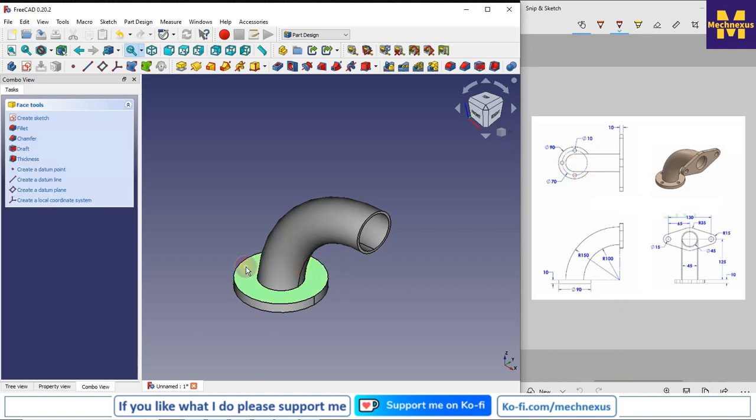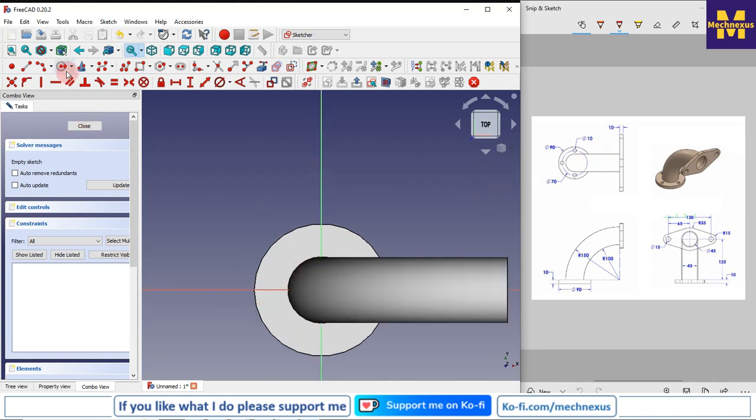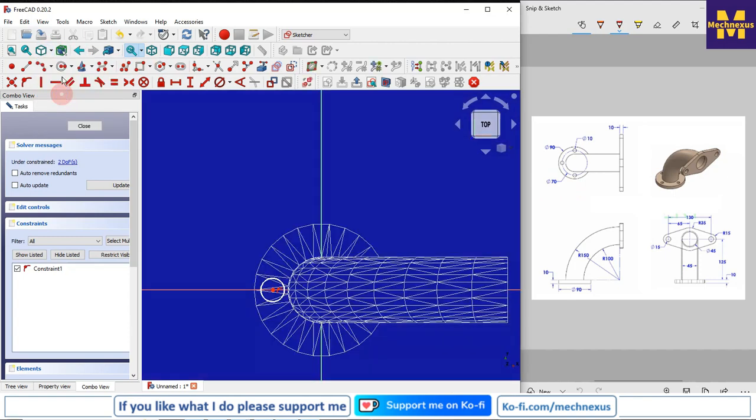So for this I will select the face, and I will create a sketch. So diameter 10, it is a plain hole, so we will just create a circle and remove the material. So I will select the circle here, and PCD is 70, so I will switch to the wireframe.